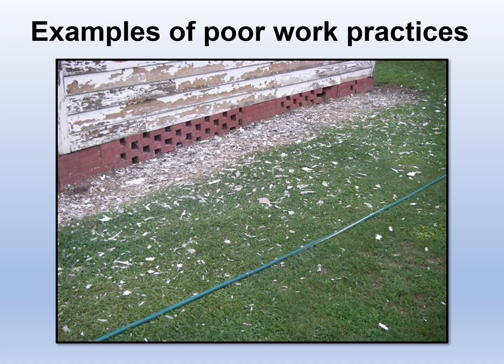Same thing here. You must contain any type of debris within the work area. There is no poly to contain it. There has been no effort to clean up the paint chips using the help of a vacuum at all.